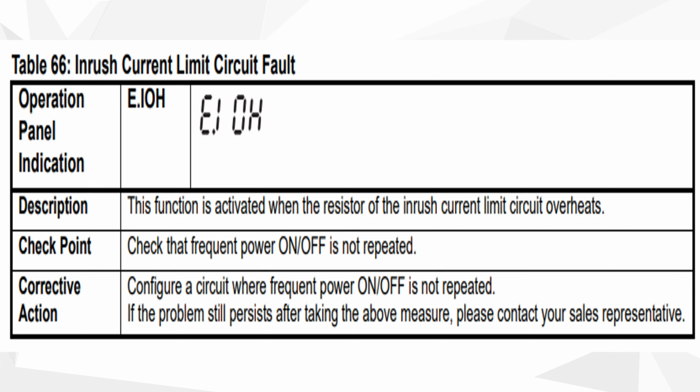We have to resolve that checkpoint where there is continuous power fluctuation, and there might be a loose connection at the input terminal L1, L2, L3 or R, Y, B. Might be this is the reason. So we have to fix both things, and it will resolve. I think it will be resolved by doing this only.